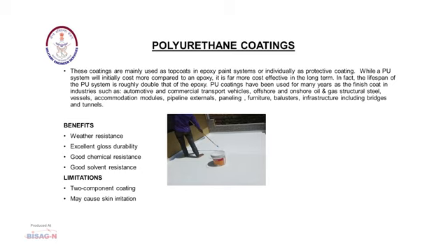Benefits: weather resistance, excellent gloss durability, good chemical resistance, good solvent resistance. Limitations: two component coating, and they are harmful for the applicators as they can cause skin irritation.